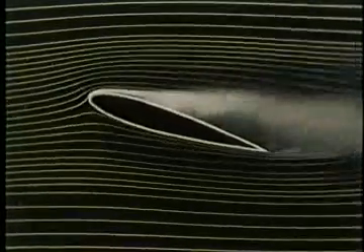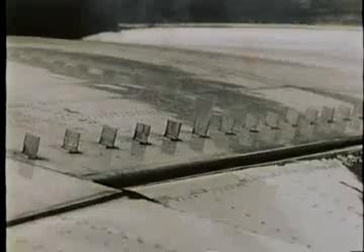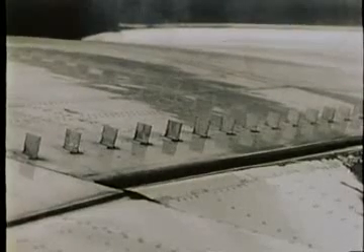The blades along this wing are called vortex generators. They introduce axial vorticity, which enhances the naturally occurring rotary momentum interchange in the already turbulent boundary layer. Such mixing delays or prevents separation.